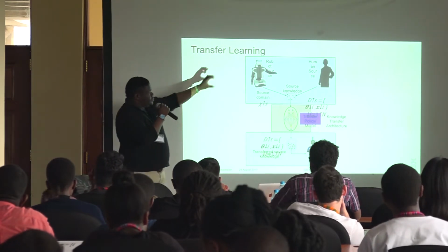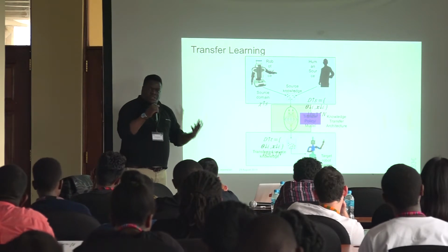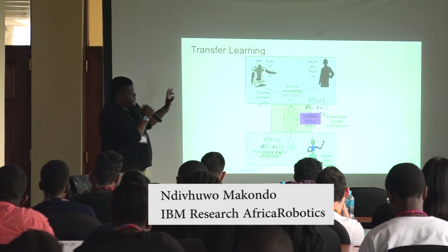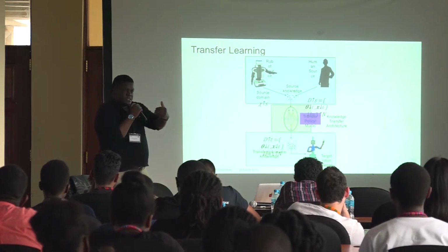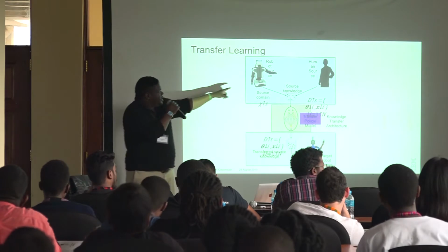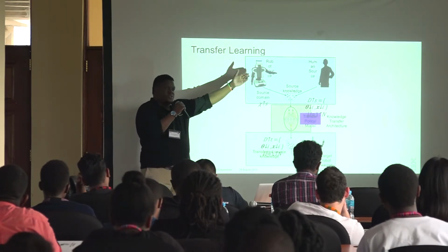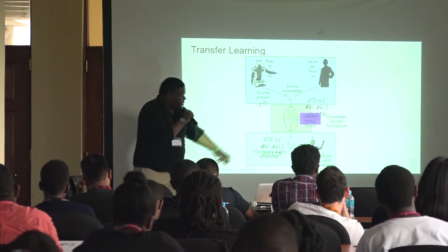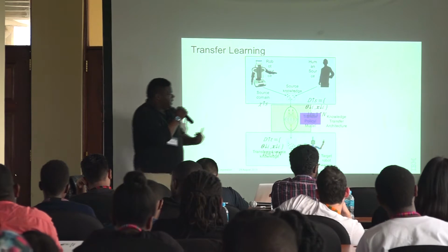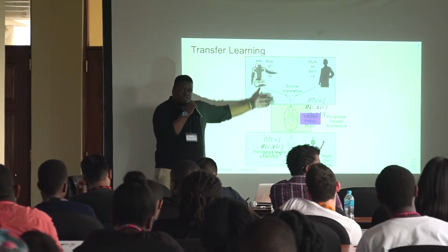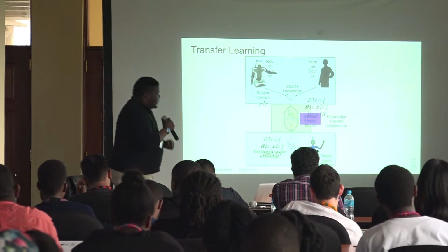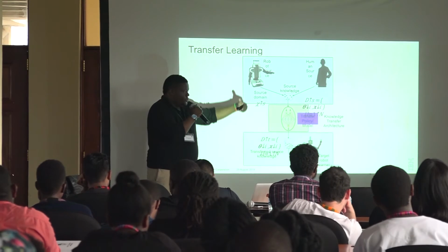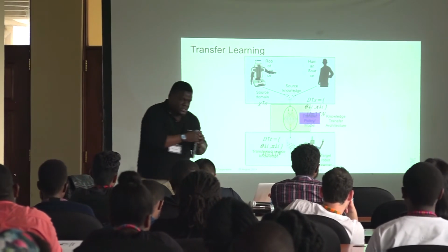But in practice, the two robots could have different dimensions, which affects the dimensionality of the data. They could also have different distributions because of the different link masses. For example, in order to track the trajectory using the PR2 robot, you may need a different torque profile compared to the target robot. So the challenge here is, how do you learn to adapt the data in the source domain in order to be useful in the target domain? The idea is learning a transfer model that you can use to adapt data to the target robot.